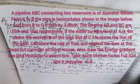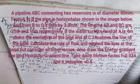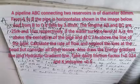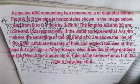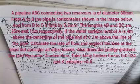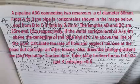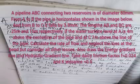If the water surface in the reservoir at A is 4 meters above the center line of the pipe and at C 1 meter above the line of the pipe respectively, the question says calculate the rate of flow and neglect the loss at the bend but consider all other losses. Also draw the energy gradient line and hydraulic gradient lines. Take Darcy friction factor f to be equal to 0.024 and K entrance to be equal to 0.5.